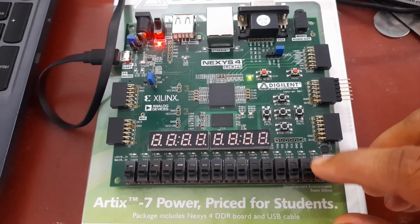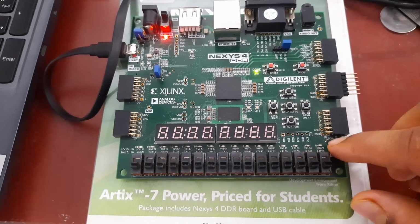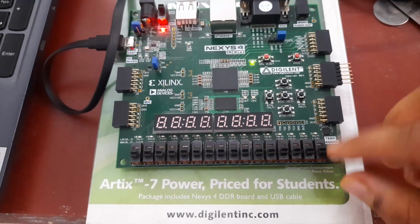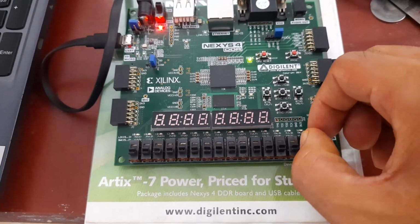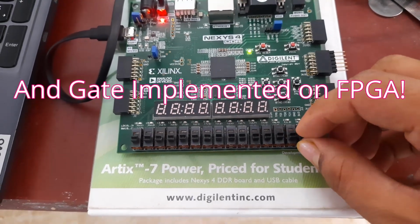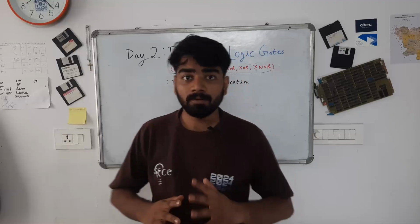First two switches were for A and B, and this LED is the output. As you can see, these are initially 0 0, 0 1, 1 0, and when I do 1 1, this LED glows. So the AND gate is actually implemented on the FPGA. Now we will implement all the other gates.